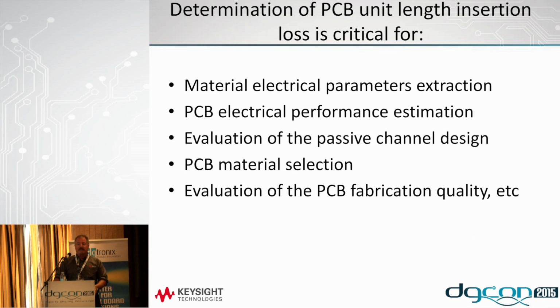It's a very inexpensive material, but it's something that has to be used in order to reach a lot of consumer applications. And so what we want to do as engineers is step up to that challenge and do the best we can to get just as fast a data rate through this material that is really not forgiving. And of course, the fabrication process of the PCBs is related to what type of insertion loss you'll end up getting in the channel.